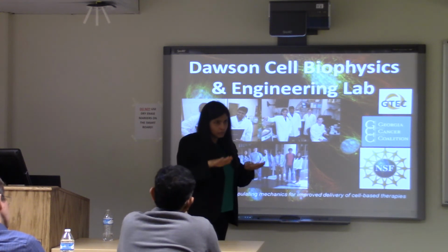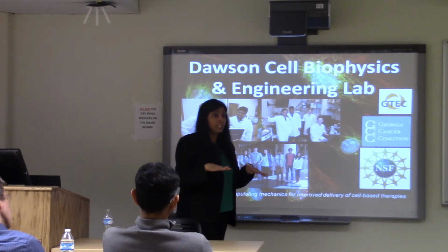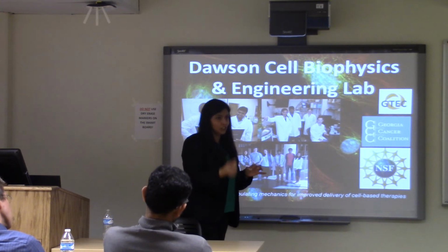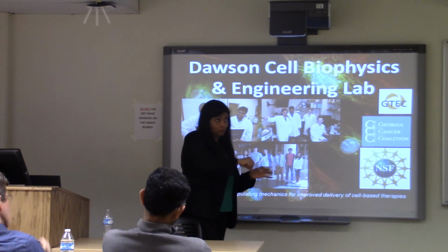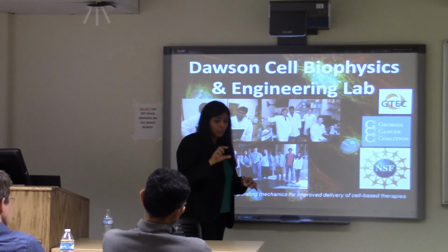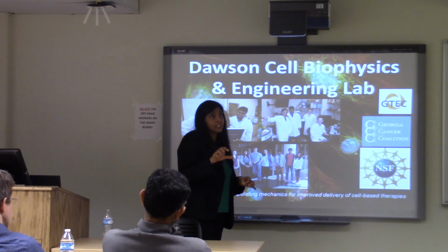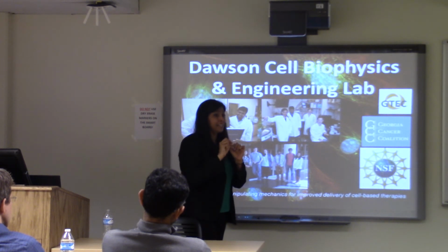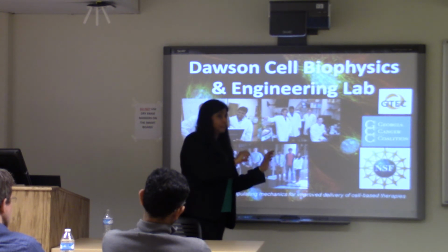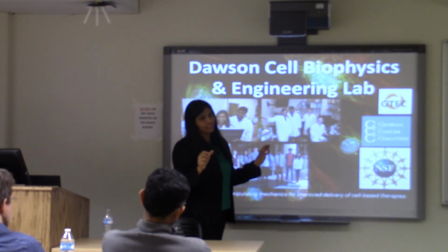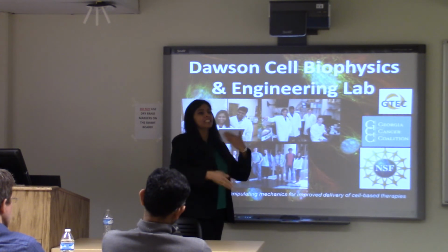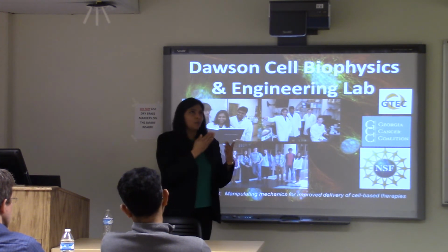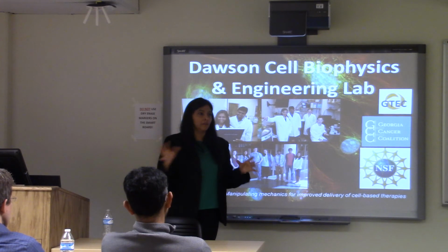And so we have these two images, and then we use a cross correlation function to determine the displacements. That gives us our strain field, and then we determine the traction stresses. There's the Green's function, which characterizes the elasticity of the gel based on the Young's modulus, and there are also other parameters in there. Then we have the displacement field, and we relate that displacement field to the Green's function and to the stress. So basically we back calculate the stress from this field.